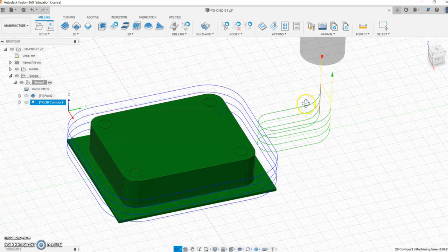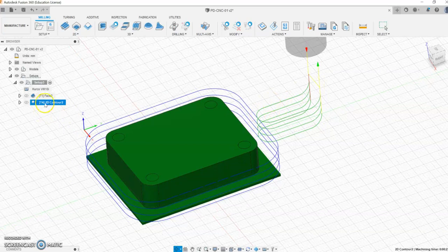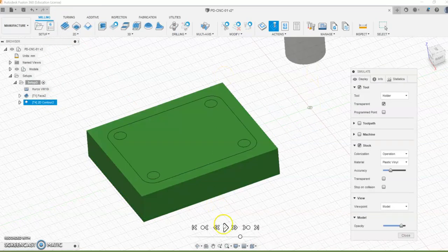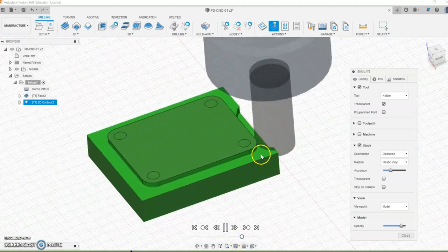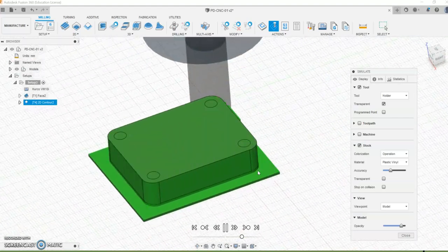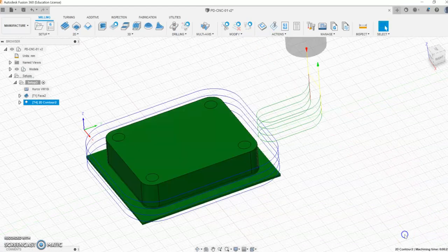So see, it took a few seconds to the end. So this 15 here is what I left on the lead in distance, and then the lead in radius. So this radius I don't really care about, but I definitely care about this radius here as such. And we just right click and hit simulate there. I'll be able to see, right click and simulate and hit play. This controls the speed here, the slide bar down the bottom. I can see it's taken 3 millimeters off, another 3 millimeters off, another 3 millimeters off. Okay, and then it's just gone beyond the part, and this part here is still clamped by the vise. Okay, so I'm going to just close that,